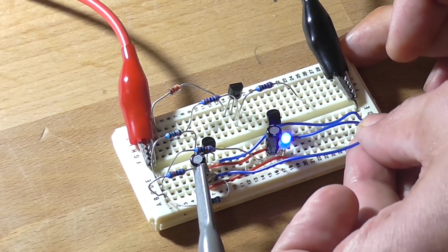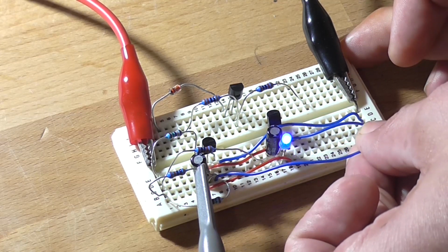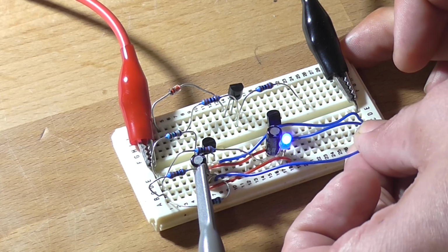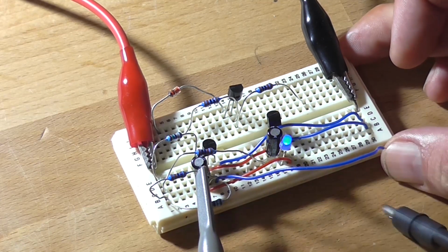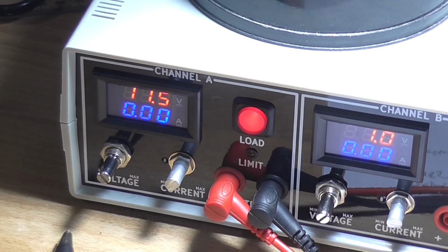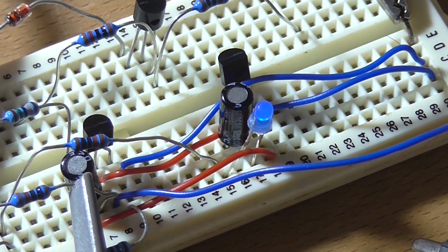That's what this extra wire hanging out in the breeze is for. If it was suddenly brought to ground on that first transistor's base, the LED stays permanently on. So you could use this as a form of power indication, fault indication, such as in an amplifier's DC protector circuit. One other thing to note is the higher that input voltage is to the circuit, the faster it's going to flash and the brighter the LED is going to be. And conversely, the lower the voltage, the slower it's going to flash and the duller the LED is going to be.